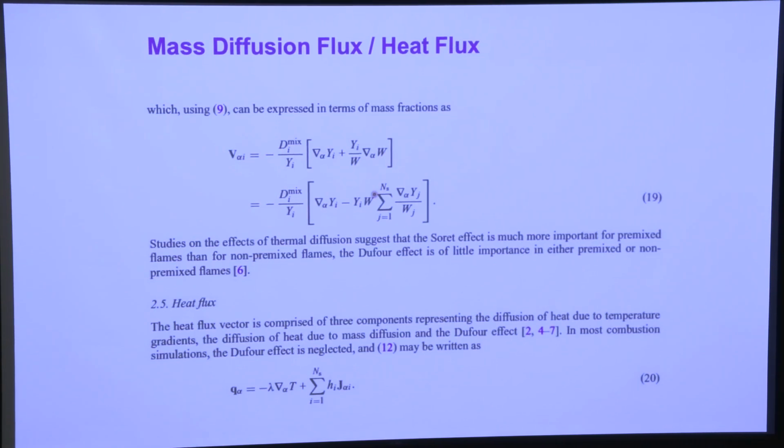And then we also have neglected the Dufour effect in the premixed or non-premixed flames, and occasionally we retain the thermal diffusion or the Soret effect for premixed flames.